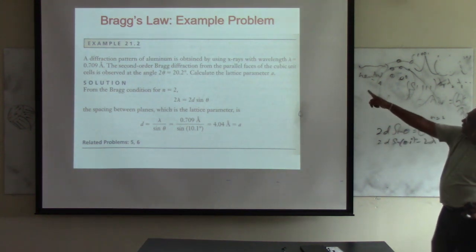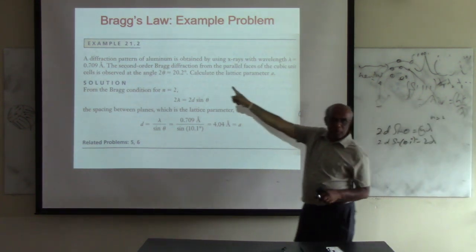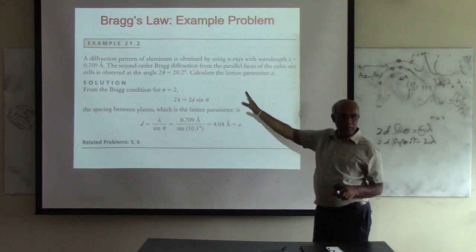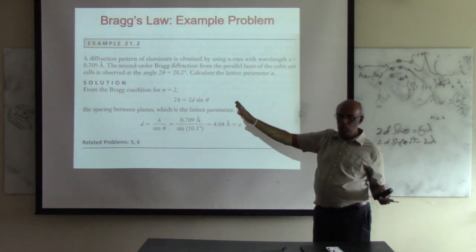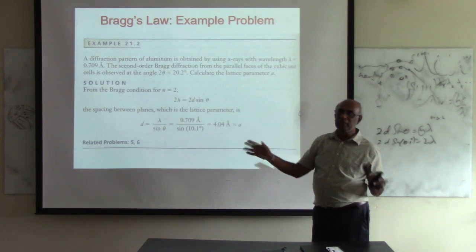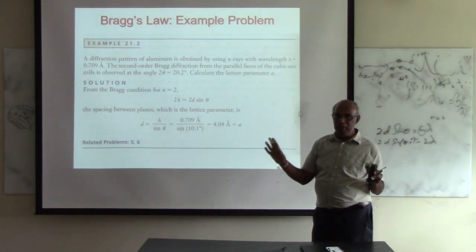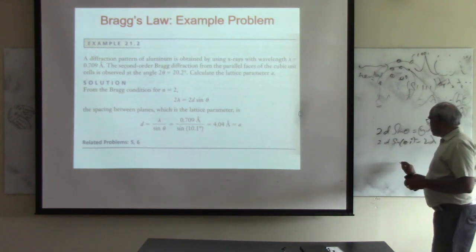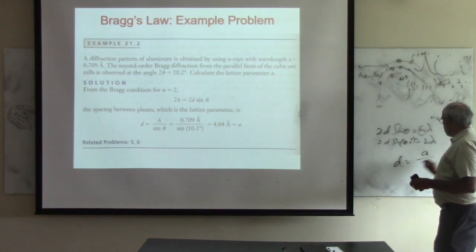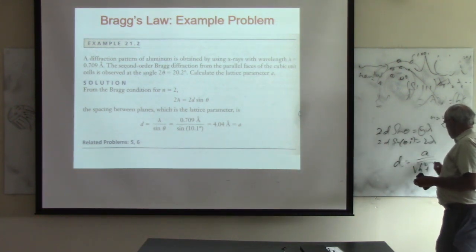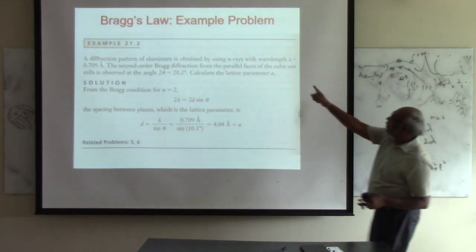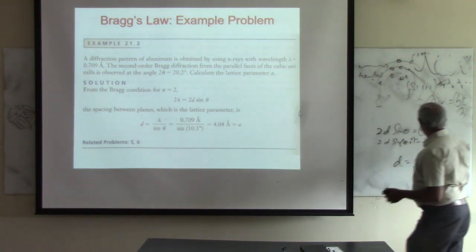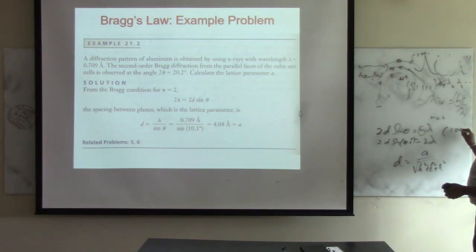So then also this is aluminum. Anybody remember aluminum, what is the crystal structure? Aluminum is usually an FCC structure, but still it is a cubic structure, right? So that means you can use d equals a over this one. But in this problem actually they are asking, this is given for the 1, 0, 0 plane, any of these planes.